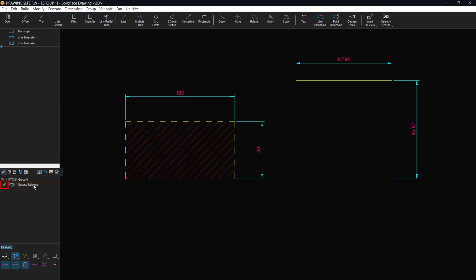To facilitate visual identification of the active group, moving the mouse to the lower area of the screen opens a View Options bar. There is an option to view all passive groups with a single color called Passive Color. Clicking on this icon activates the option to display all passive groups with passive color. There are 3 ways to activate a group. Double-click on an entity belonging to a passive group. Double-click on its name in the group list or click on the plus icon.